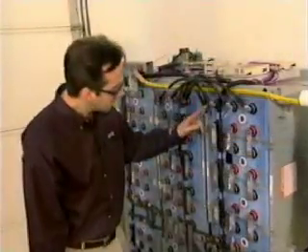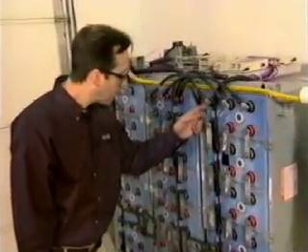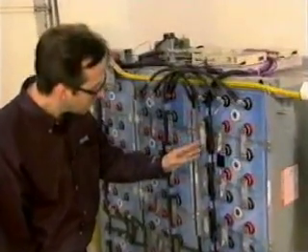As for the value of conductance testing, there is an understanding that a linear but not direct correlation exists. Also, as you test and compare the results with the history of the installation, look for trending. What is changing and how quickly are the changes happening? Ideally, battery strings should be examined regularly. Every 3 to 6 months is recommended. Recently installed cells should be examined as well.